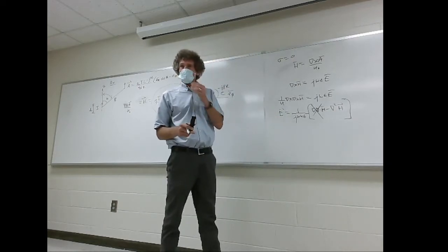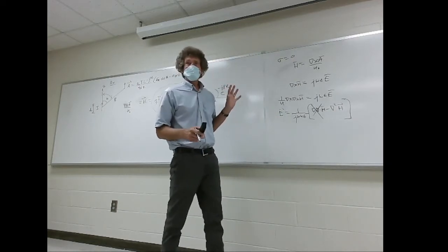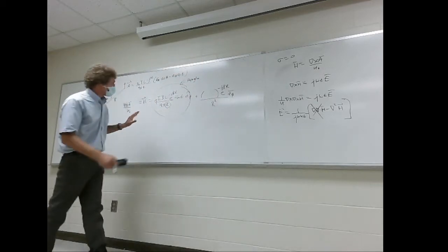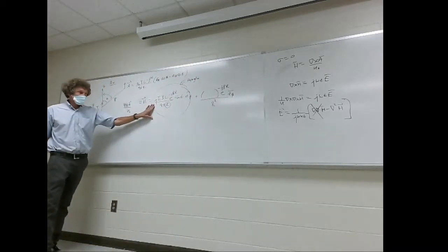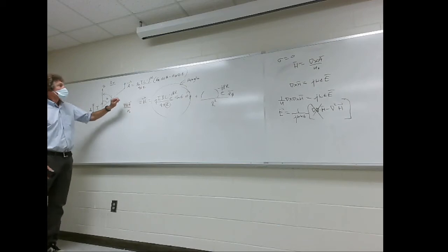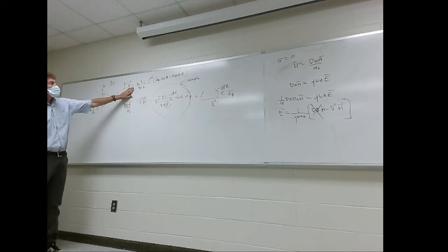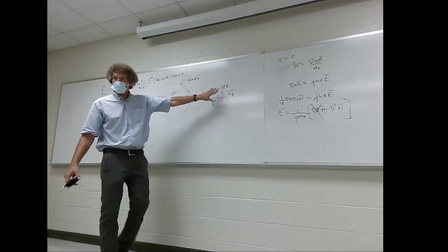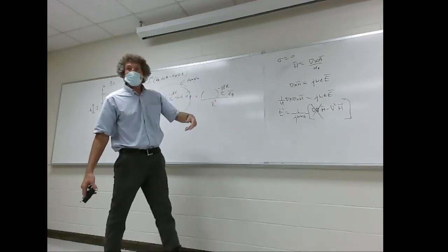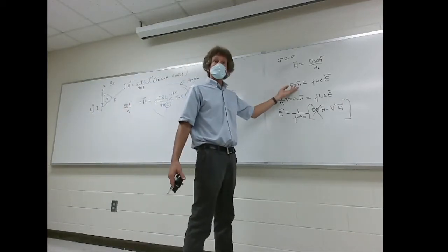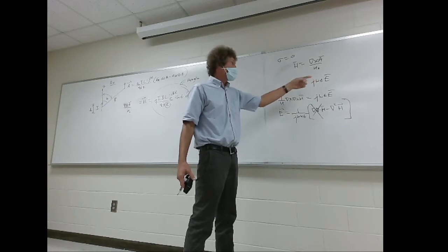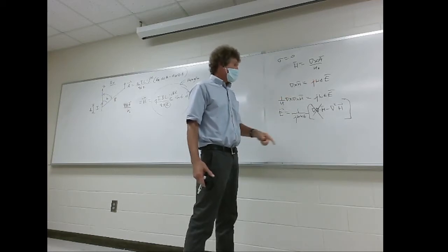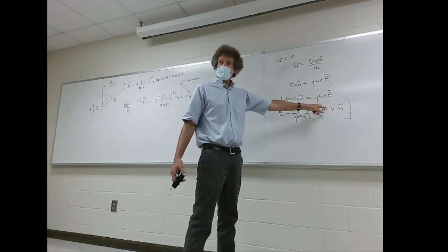Now, there are some tricks to this, but I wanted you to understand something. If you get A as this, from a short dipole, and you take the curl of this, which has to be done in spherical coordinates, you're going to get this plus another term. If you took the curl of that H and divided by j omega epsilon, you get E. Or if you had H, you could do that and get E. That's a second order derivative.